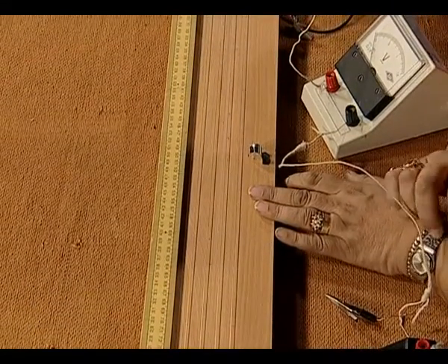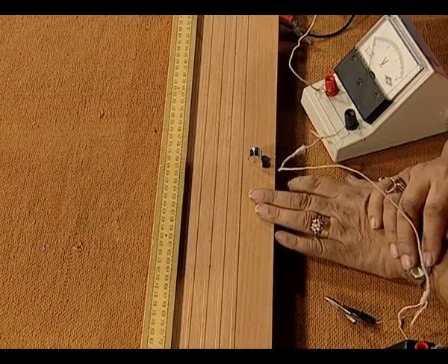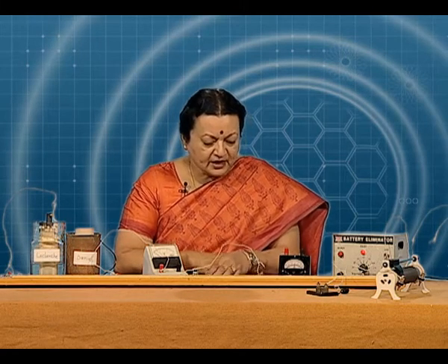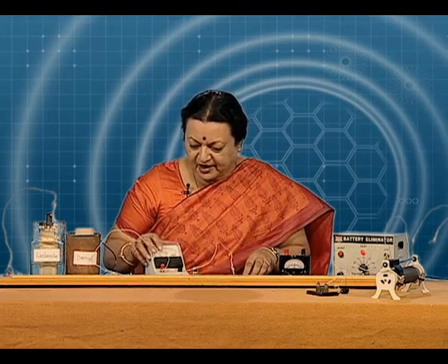If we are to recall the principle of potentiometer, if a steady current flows through a wire of any length, then the potential drop across a certain value of length remains the same, provided we have a homogeneous wire having same area of cross section, having same resistance per centimeter of the wire, and there is no change in temperature, or it could be a low temperature coefficient wire. So, let us see if that is happening in our case.